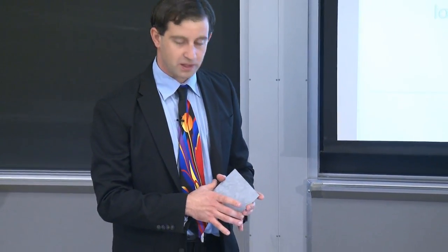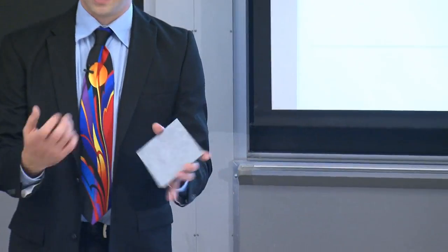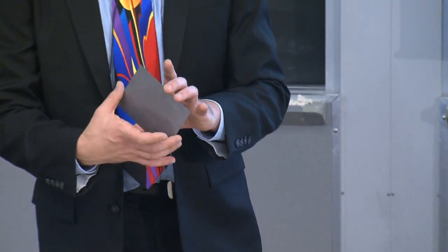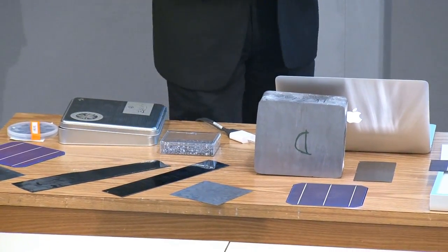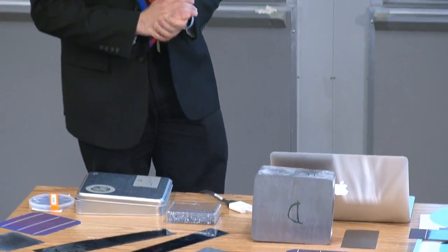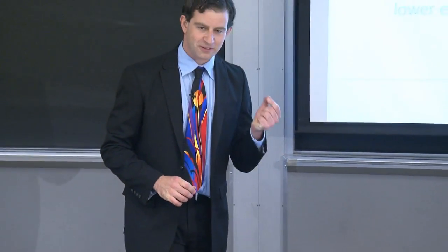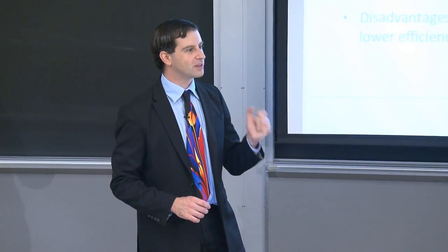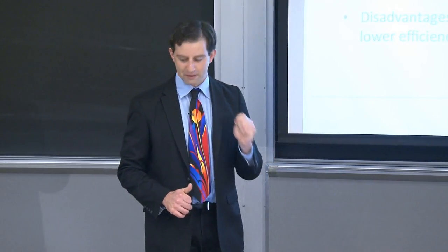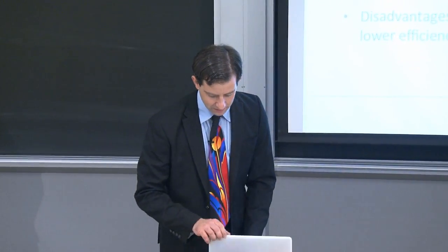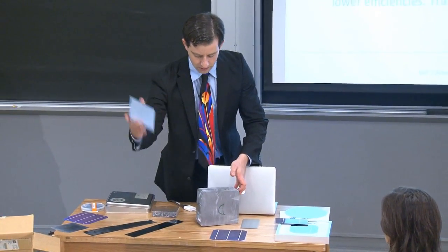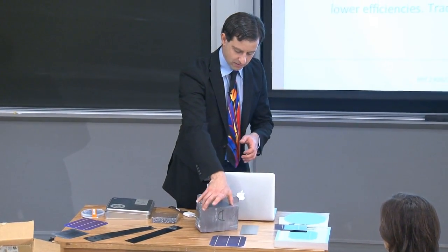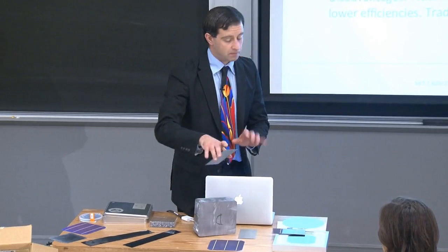And as a result, typically thinner wafers are used and less expensive starting materials and faster growth methods, resulting in more defect-rich materials. So one group decided, gee, the embedded cost in the wafer is just so large. It's just so large that we have to make it thinner. And we have to avoid using these ingots, like this one right here, from which these wafers are sawn, right? So you take your wafers are sawn out of the ingot like this, like shown.